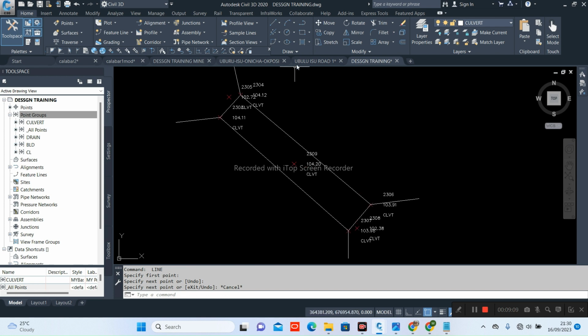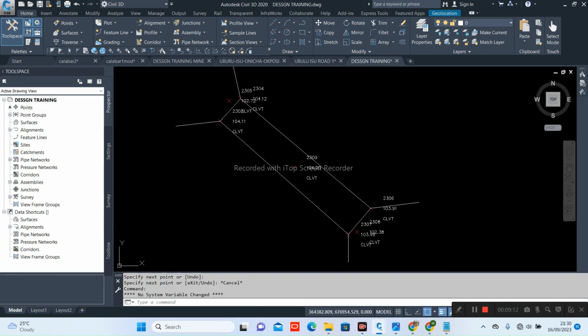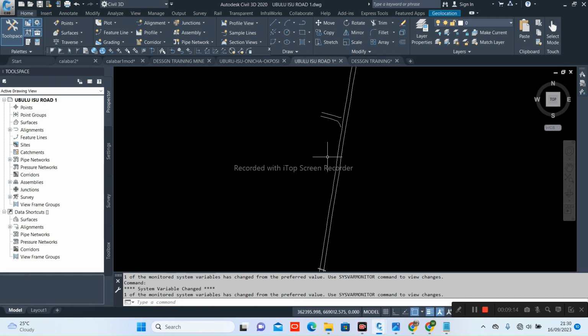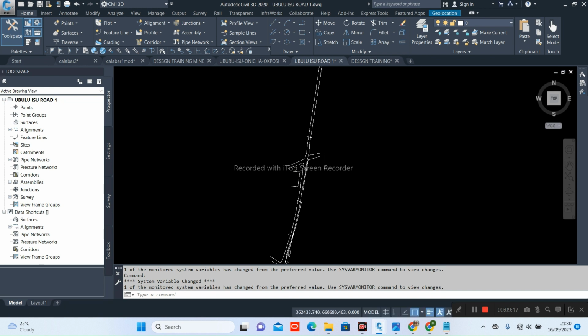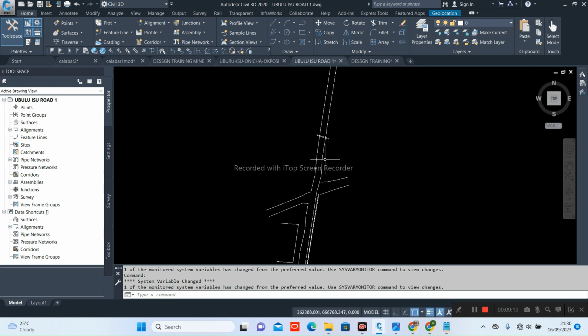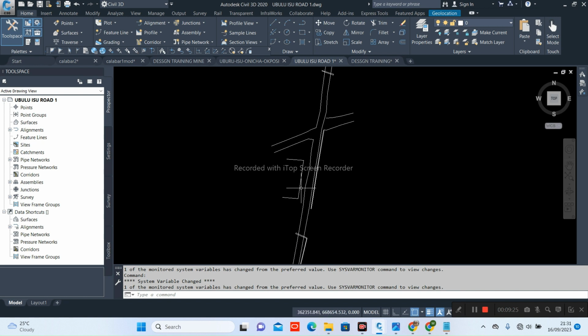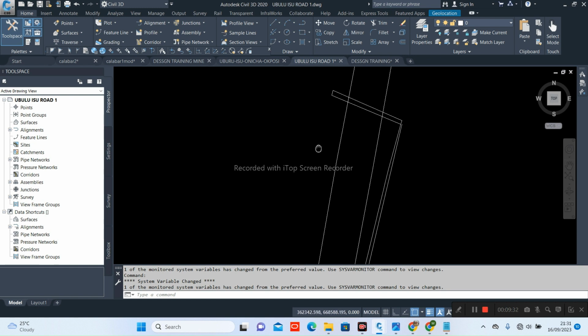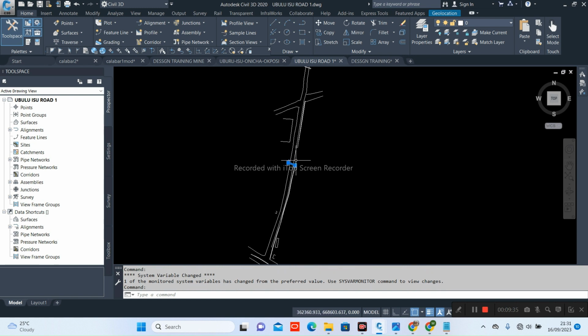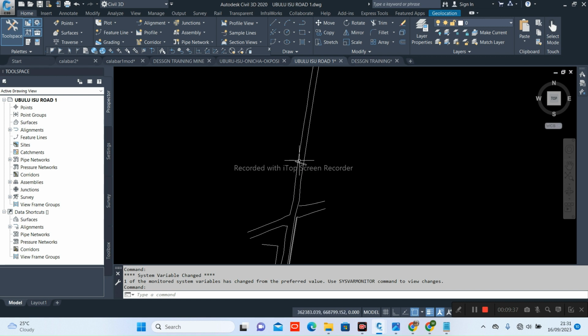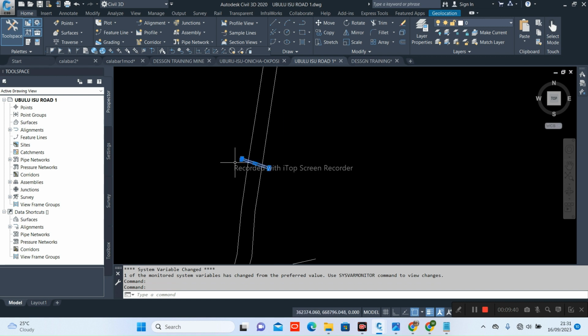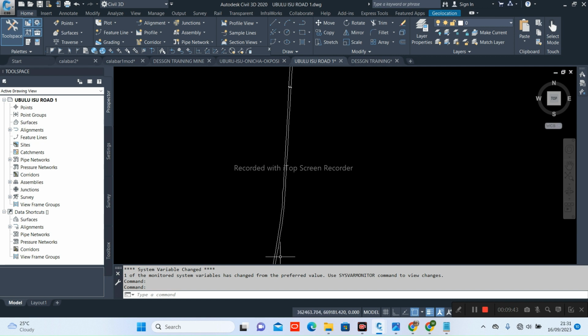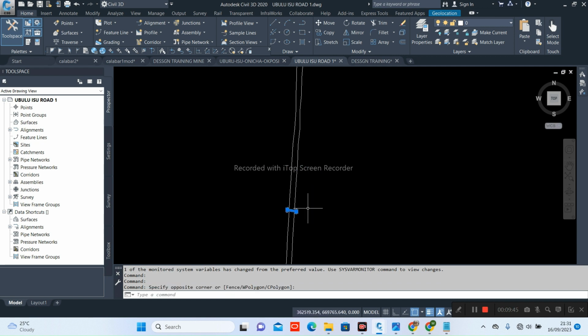So what you need to do is just to open the drawing. Like this one for this road, you can see it was done by the surveyor. These ones are the edges of the road. These are buildings. So what I will just do, I will come here. Some of them don't use layers, so it's difficult to just turn that off. I'll come here, pick. The reason is a lot of them use polyline, so it makes the work easier. So you pick the culverts and their locations.